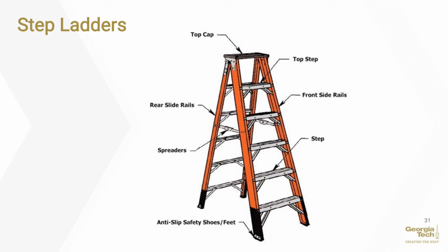Common stepladder hazards include damaged stepladders, ladders on slippery or unstable surfaces, unlocked ladder spreaders, standing on the top step or top cap, loading ladder beyond the rated load, ladders in high traffic locations, reaching outside the ladder side rails, and ladders in close proximity to electrical wiring or equipment.